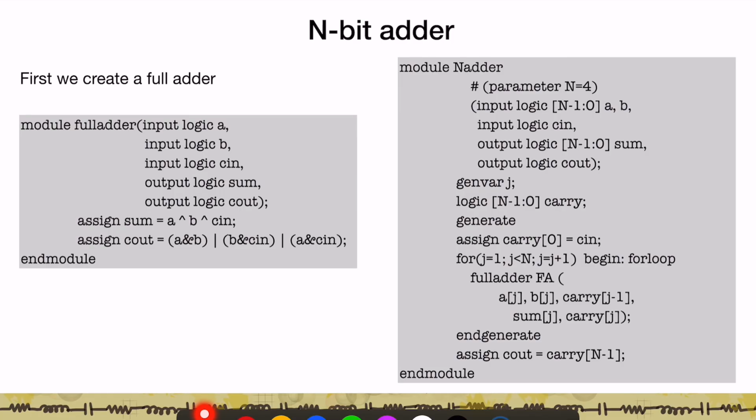Now the key thing to keep in mind with generate is that while it is powerful, you can have a tendency to create circuits which are very large if you let it run uncontrolled. You have to be wary that eventually you're writing Verilog code for hardware. So there are practical limitations on how much hardware you can stuff between, say, different clocks. Be very careful, because there is a propensity to generate useless hardware if you use the generator. Even though you might think you're doing an optimization, you might end up creating junk hardware. So while the generate term is useful, use it with care.